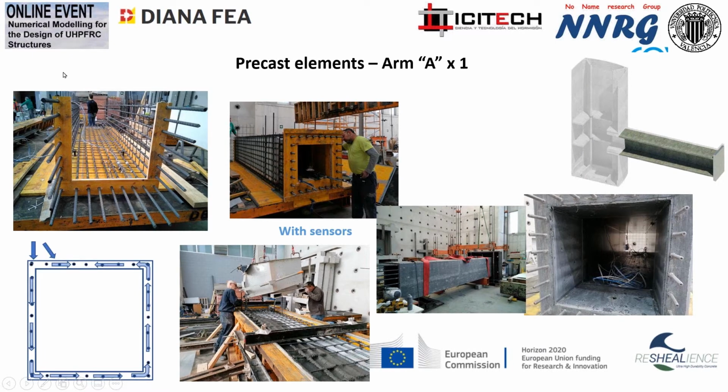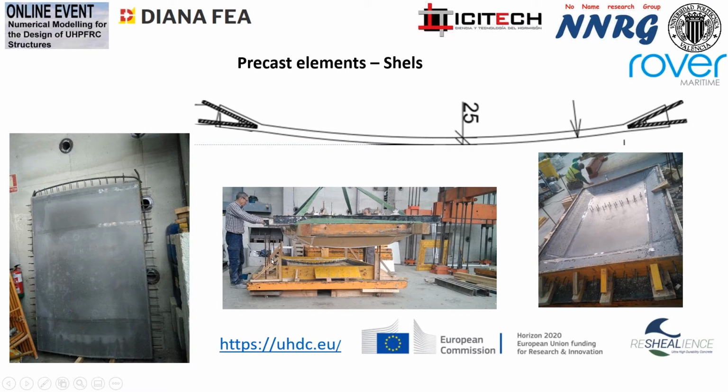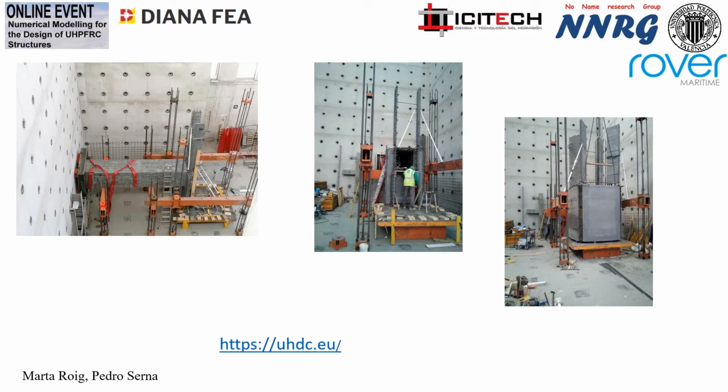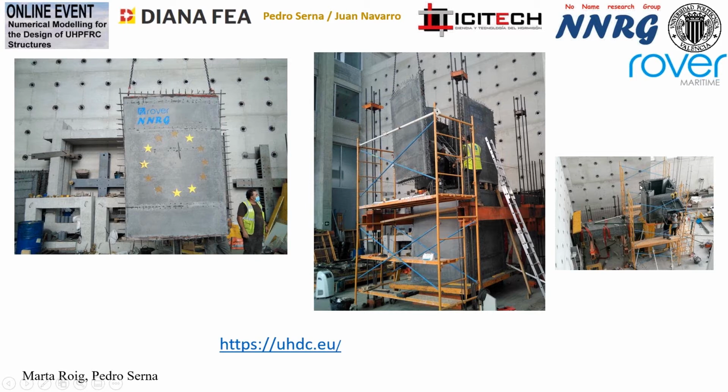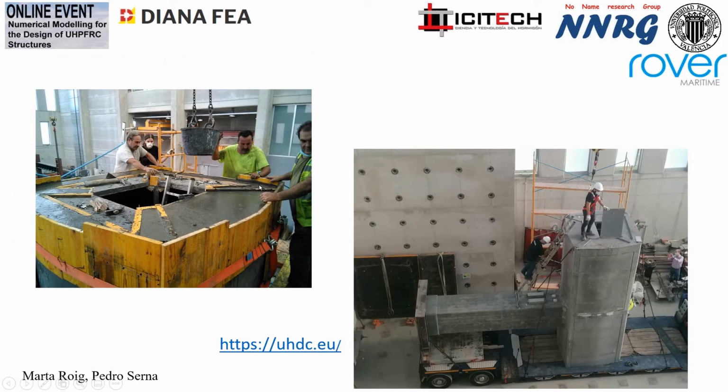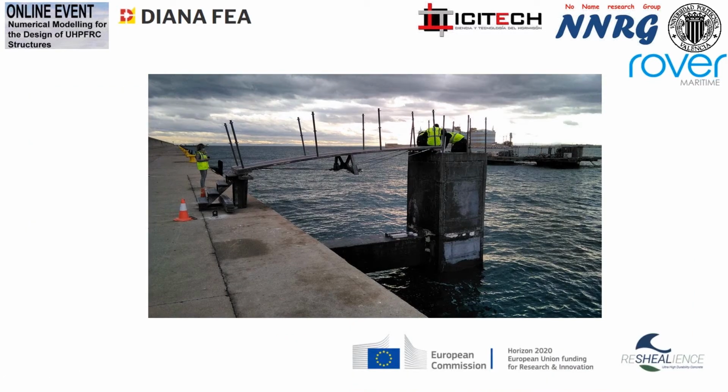Okay? Then, of course, the arm has lots of rebar, but the idea is to put concrete in by here, concrete goes by here, and goes to the top. And then we can guarantee that all the concrete is well oriented and that you have no cold joints. We perform the lateral in the same way as the previous one, by counterpoint to guarantee the surface. This section is 2.5 centimeters. We do it like an IKEA product. We can do the assembly of all the elements, we connect them, pour the concrete in the section, and transport everything to the foundries.